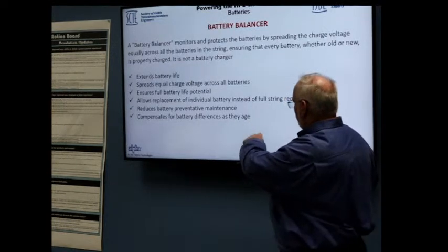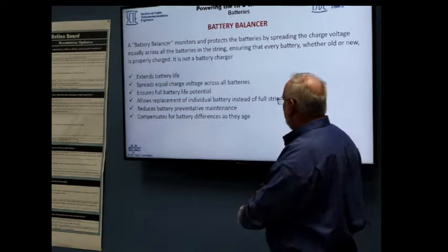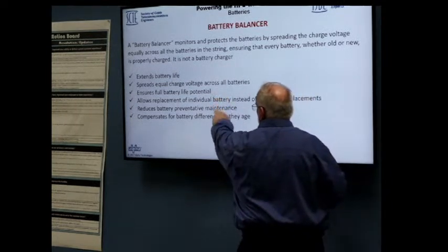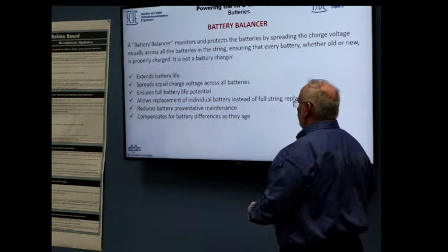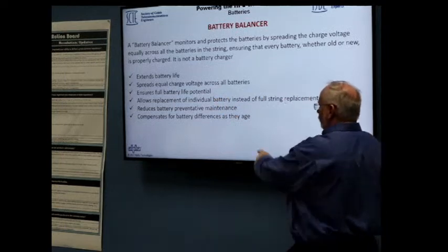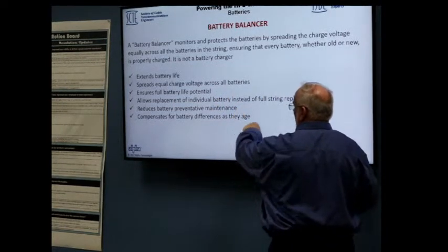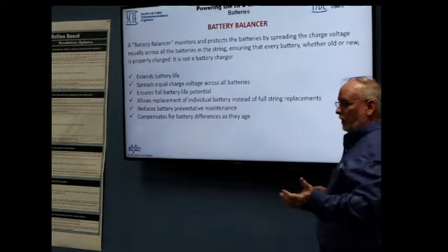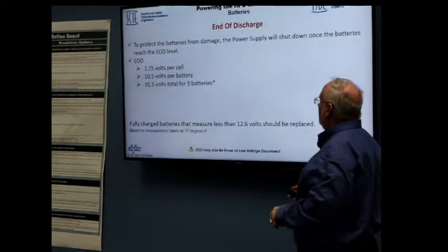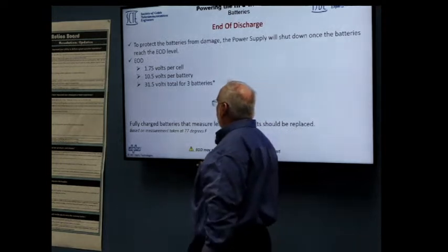Battery balancer, I think I went through this pretty well. Ensures battery life potential. That's the biggest part right there. It allows replacement of individual batteries instead of a string replacement. It reduces the battery preventive maintenance. It allows you early visibility into weak batteries. Again, end of discharge, I talked about this too.